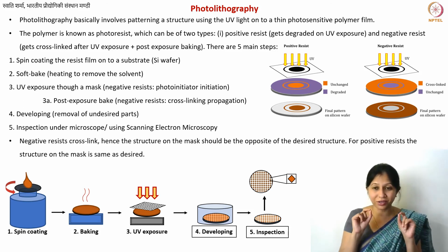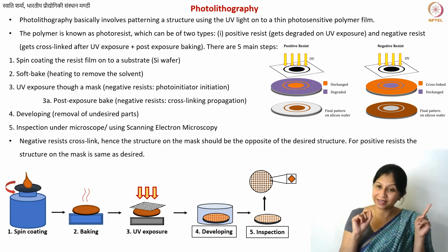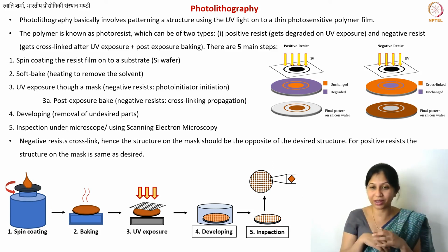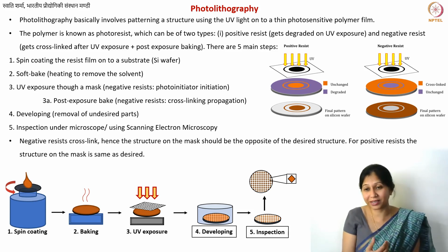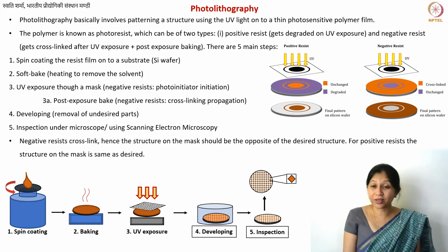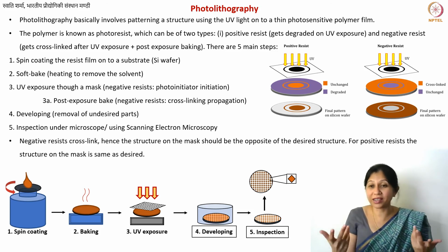Remember that these structures will be dimensionally smaller. They will be shrunk. That is the same problem we have in large scale manufacturing: you end up losing some material because it becomes smaller. But here you can even utilize that fact, because smaller structures will have a higher surface area. So smaller is better in the case of micro nano fabrication, right?